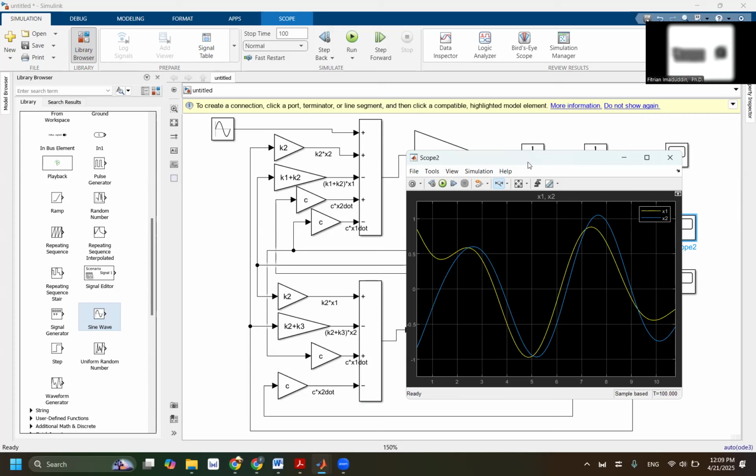In one of the simplest representations, you have the mass of the car supported by a spring and a damper, and you have the mass of the wheel supported by the representation of the K of the wheel, and also the C. So this is the K of the suspension, C of the suspension, K of the tire, C of the tire.